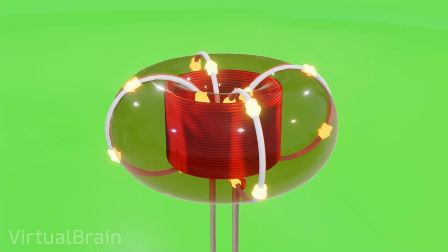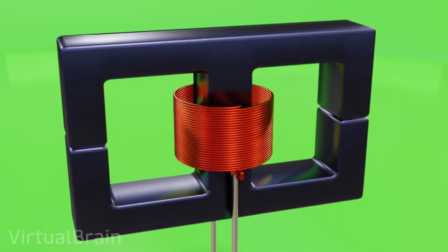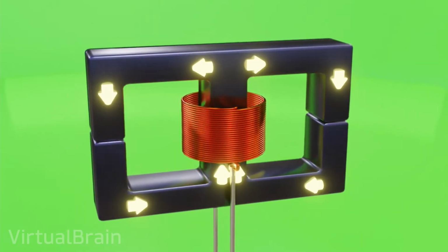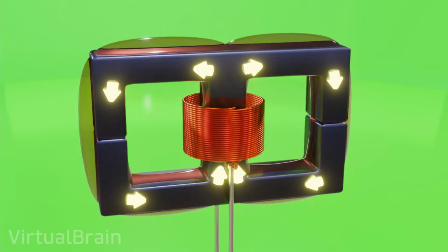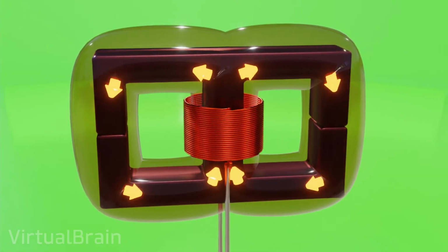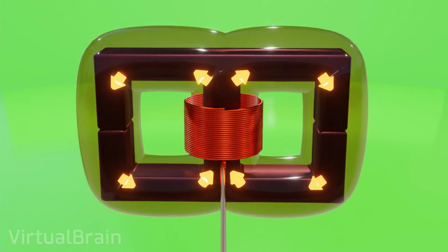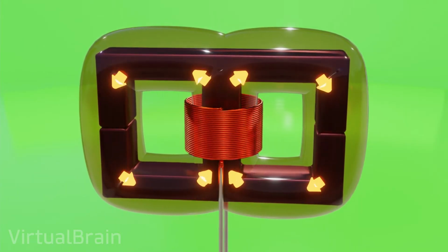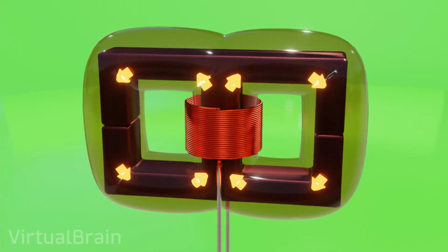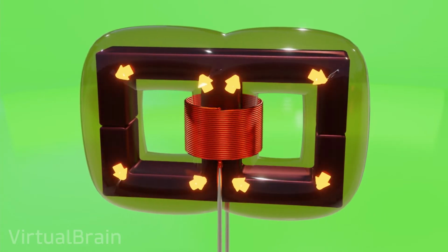If we add a core to this same coil like the one with the shell-type transformer, this will serve as a guide for magnetic flux, and therefore we could say that we now have a magnetic field in the shape of two toroids. Even though the mere fact of using a core will already considerably increase the magnetic flux, this design is not optimal, because the induction effect on the secondary coil occurs mainly in the center, where the coil completely surrounds the core, that is, only a limited section with respect to the total available area.